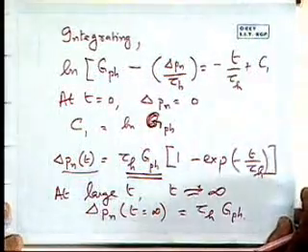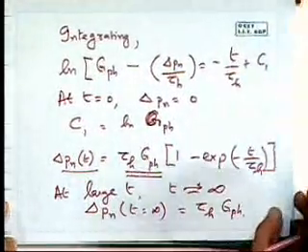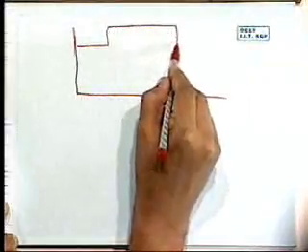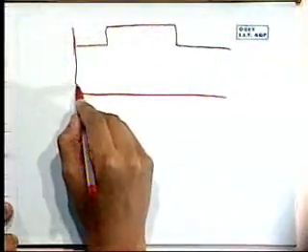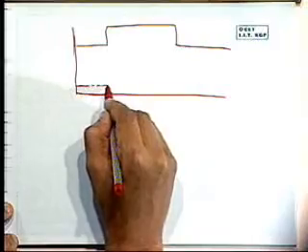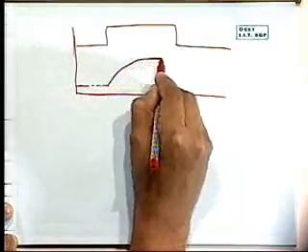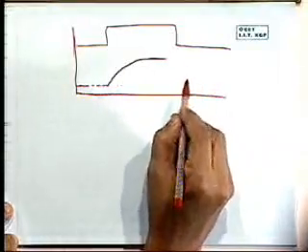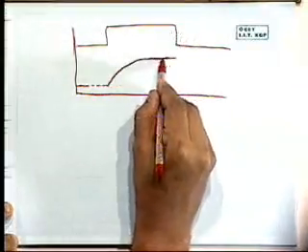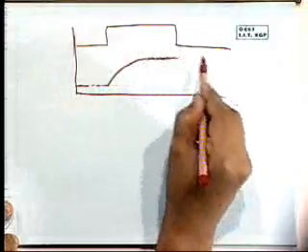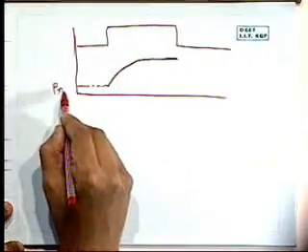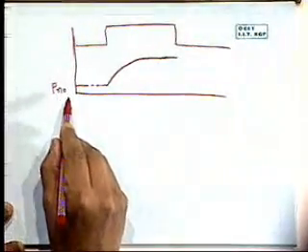So far what we have can be sketched schematically. I turn on the light at t equal to 0, and there is some minority carrier concentration. It is going to rise exponentially to some value, and then it saturates. No matter how long I keep that light on, it's not going to go beyond that. This was my original Pn naught, the equilibrium value for the minority carrier.